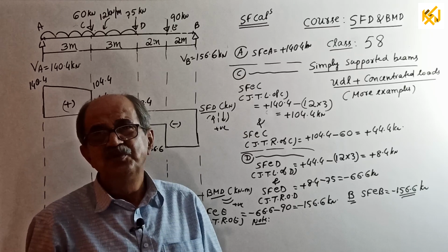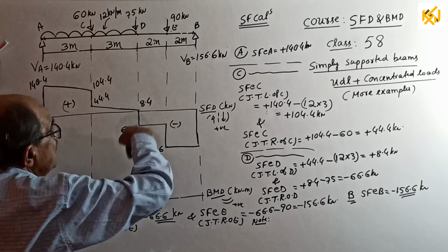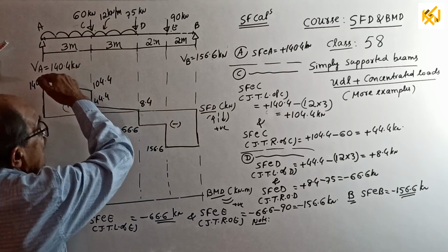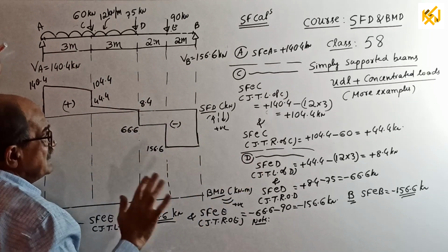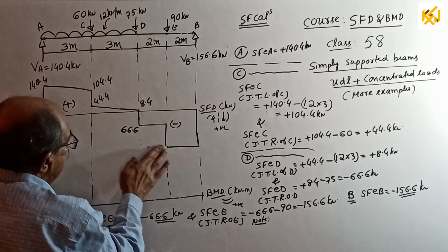So you should tell, when point load is there, shear force will suddenly change. When UDL is there, it will gradually change. That's all required. Okay, leave it. Their choice. Start. I write here